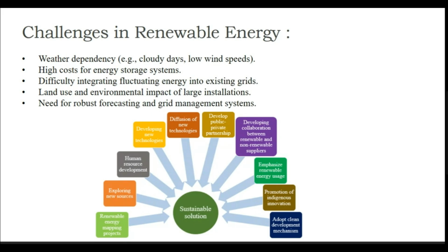A basic rule of electrical engineering is that when you are paralleling two systems, the voltages have to be the same. When the voltage is fluctuating in one of the devices, then when we parallel it, the device with the least voltage would be affected. Hence, this is a major concern when paralleling a renewable energy source to the grid. So here a power electronic device comes into the picture, which tries to maintain the voltage when it has been paralleled. These are some of the drawbacks in connecting renewables to the smart grid.